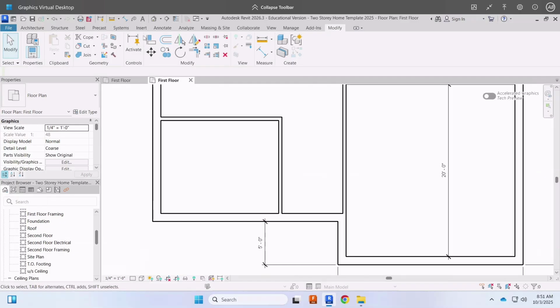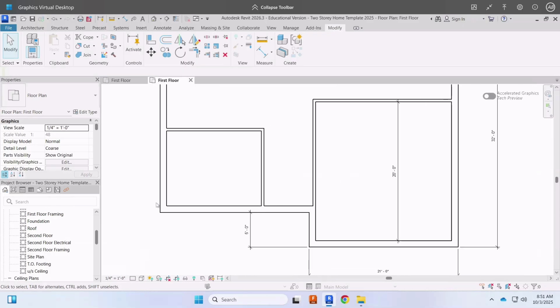So you're going to go around and do this, put all your walls in, and then dimension to size. Remember that your interior dimensions are going to be smaller than what you have on your line drawing, just because now we actually have wall thicknesses. You can't change the outside because you have a max limit on your width, so you're going to have to alter the inside dimensions a bit.